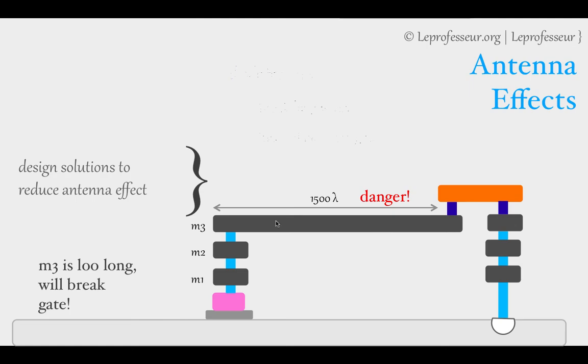The second solution is to insert a diode near the gate, so that whatever extra charge is built up can be sucked by the diode. The extra charge buildup will get routed to ground via the diode, or in other words, the diode will suck up the extra charge, so your gate will not get affected by that extra charge and will be safe.